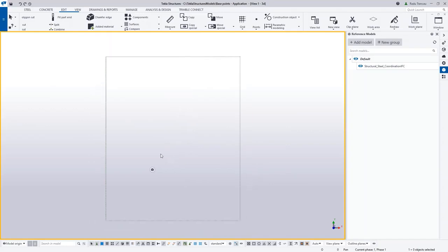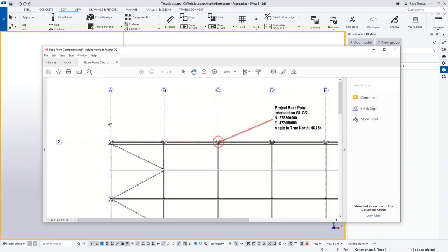You can do that in 3 different ways. The purpose of the three methods is to bring the IFC closer to the Tekla origin. The most straightforward method is just to create a base point based on the information that's been given to you. That information sometimes may come from the architect, or from the BIM manager, or from whoever. You've got this information at the ready.